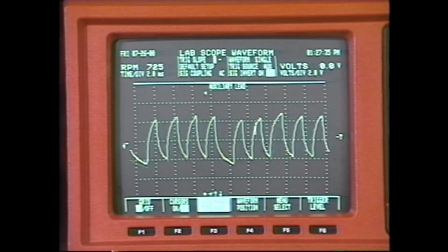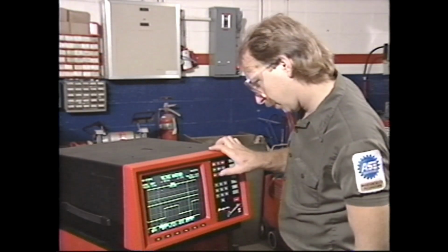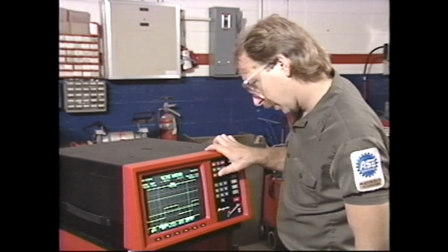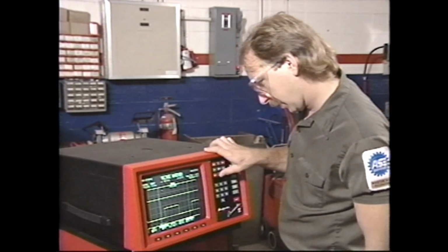You should know whether the signal is analog or digital, what the specified voltage amplitude and duration are, whether a device is controlled on the feed side or ground side, if the signal's duty cycle is fixed or variable, whether the frequency is fixed or variable, and what normal system operating conditions are. You should also be aware of outside factors as well as things you might do that can affect signal integrity.